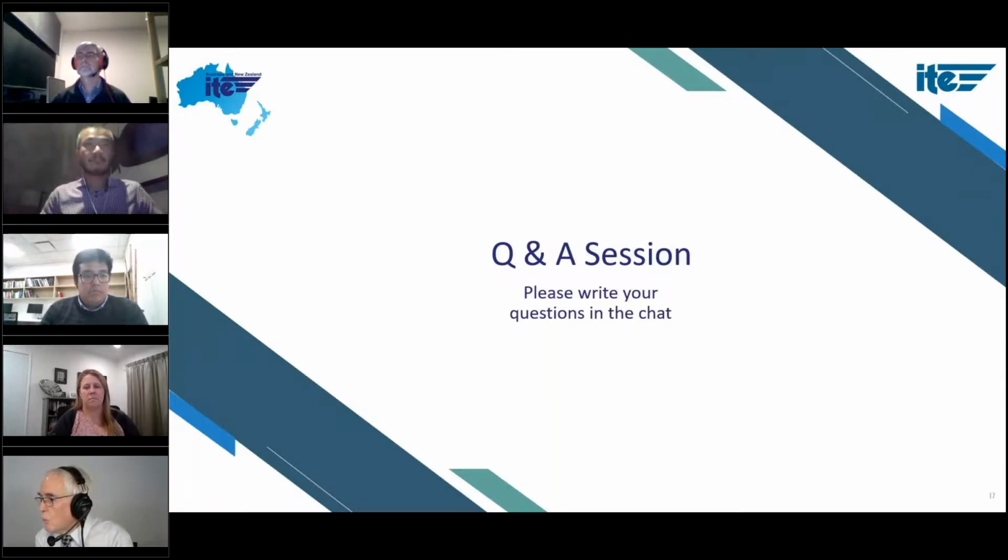And I think it would give you a good saturation flow value. With a little more detail, you might perhaps calibrate it slightly to give the same results as SIDRA, but from what I can see, I would expect it would give a good saturation flow to work with. So yes, I would endorse the use of that. Thank you.